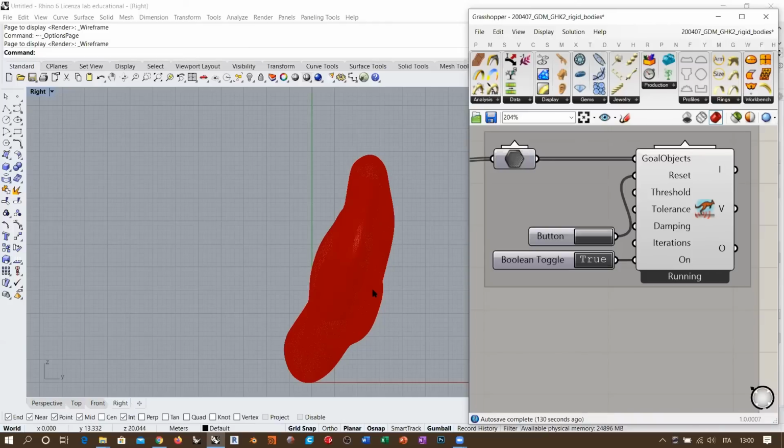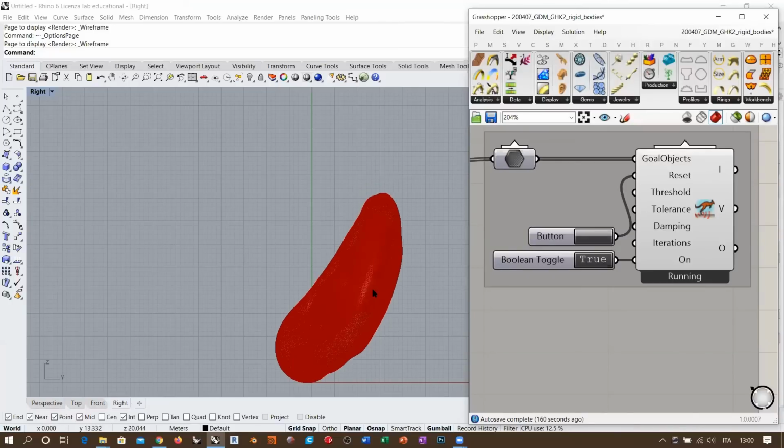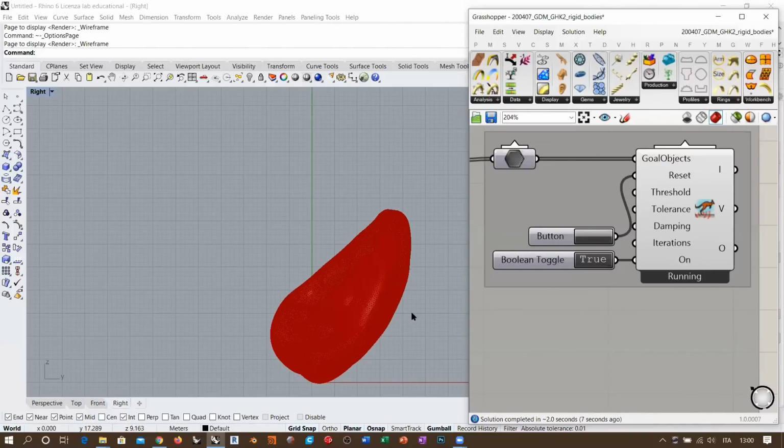And the rigid body is absolutely more effective than the floor. In this particular case, with 40,000 vertices, you might also work with the floor, because we have 40,000 points all around this body here. So it will be basically the boundary representation, meaning the external surface that won't be able to pass through the floor, and not the barycenter.